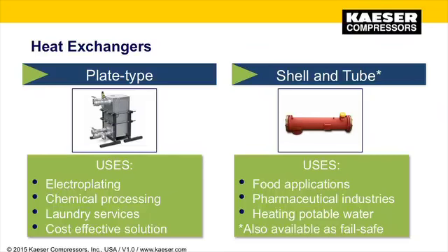A pressure monitor on that intermediate fluid chamber is monitoring for any possible leakages on either side and will provide an alarm signal in case of a breakthrough to allow shutdown of the system before the contamination occurs.